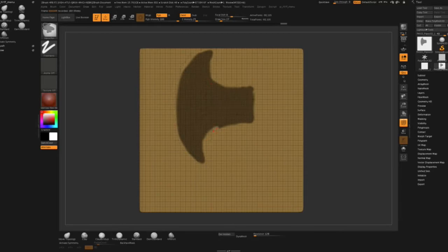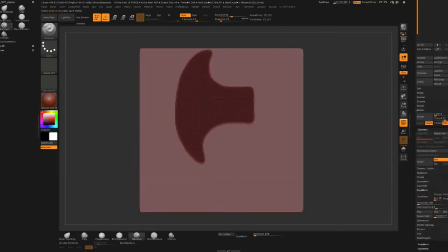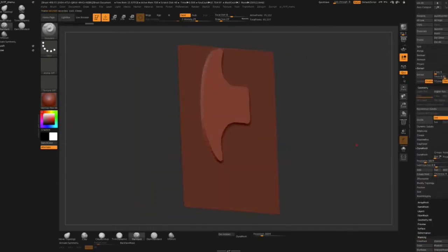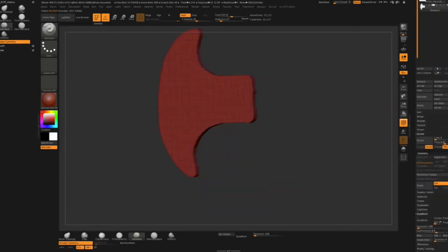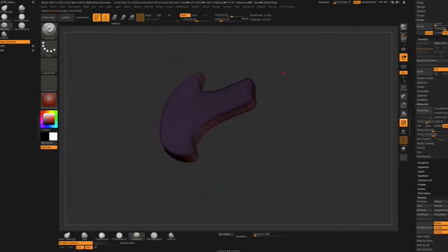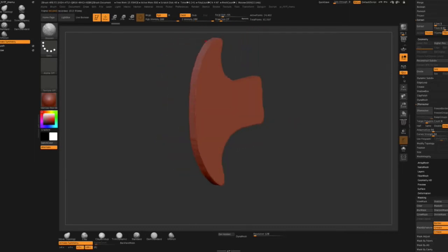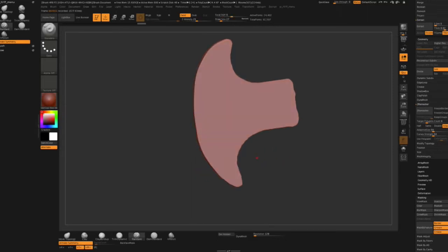Use Ctrl and Alt together to clean up the border area. Sharpen the mask. Set the proper thickness and extract the shape. Use ZBrush to convert the geometry to a better topology. Then smooth the edge.